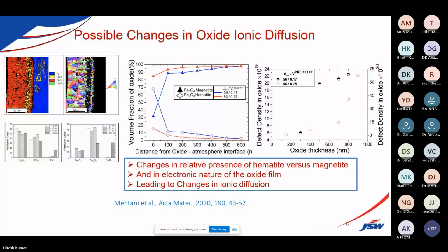30 to 100 microns around. 30 to 100 micron. So it's going to be difficult, because in EBSD you understand you are tilting it at 70 degrees and then putting it for a longer run. So what you can do is take the powder and make it into the form of a pellet.